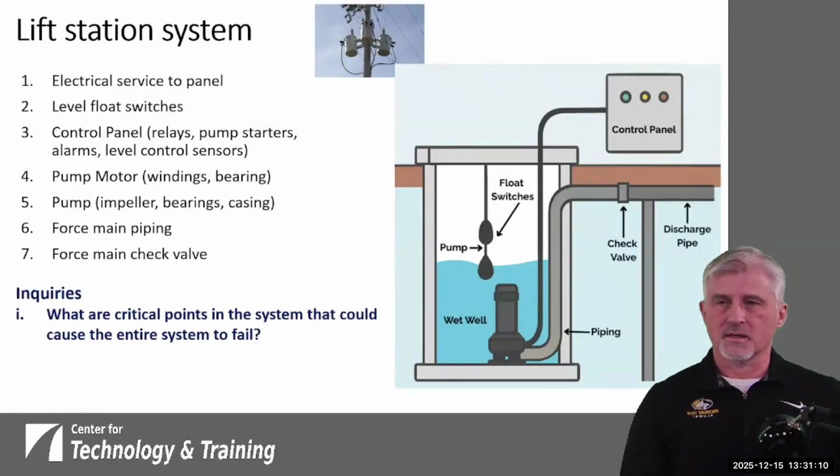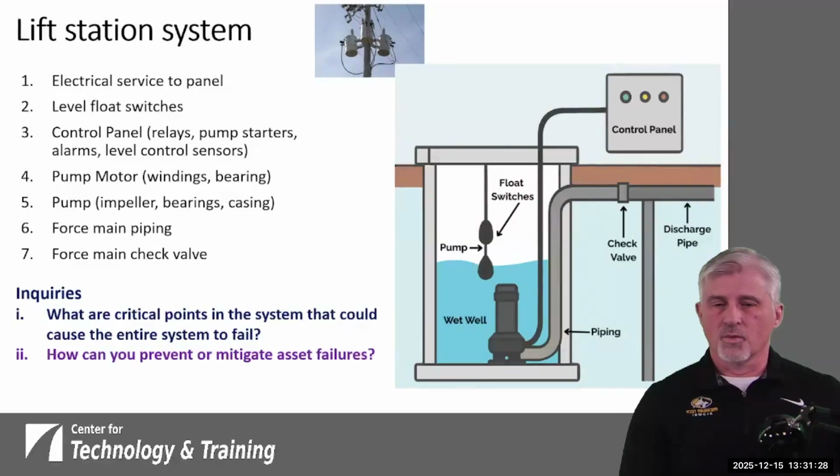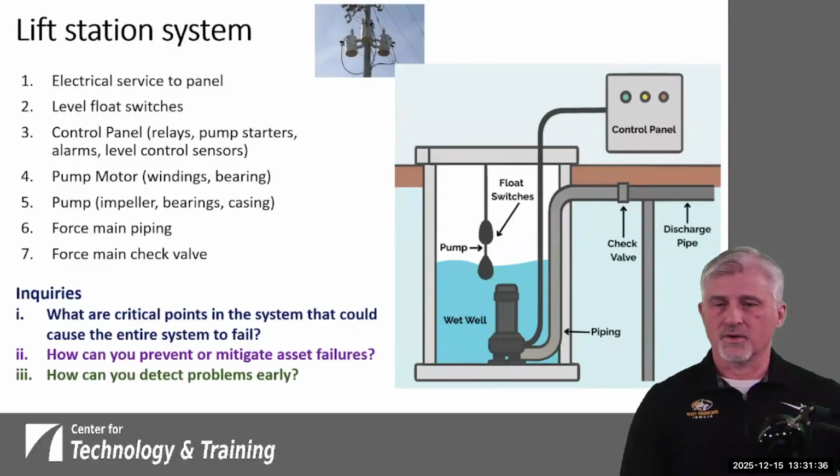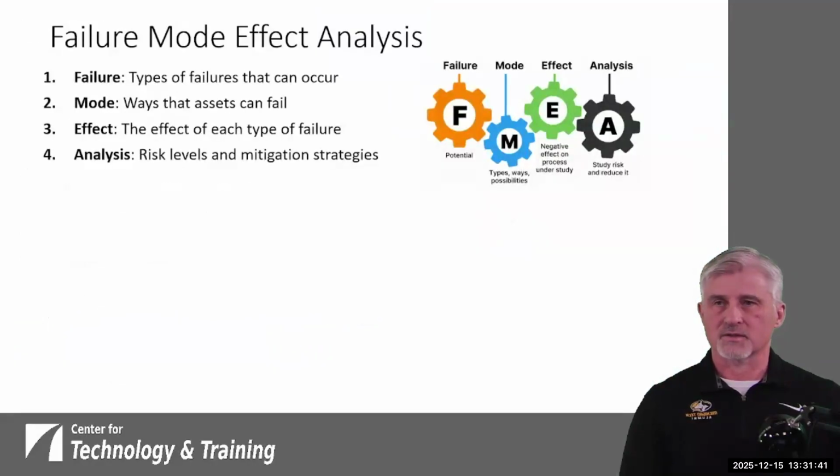All right, so what things do we have to think about? What are the critical points in the system that could cause the entire system to fail? If we're going to look at this lift station system, we've got to look at what are the critical points that could have the entire thing failing. And we also have to look at how you prevent those assets from failing, and what you can do to detect any problems early on in this process.